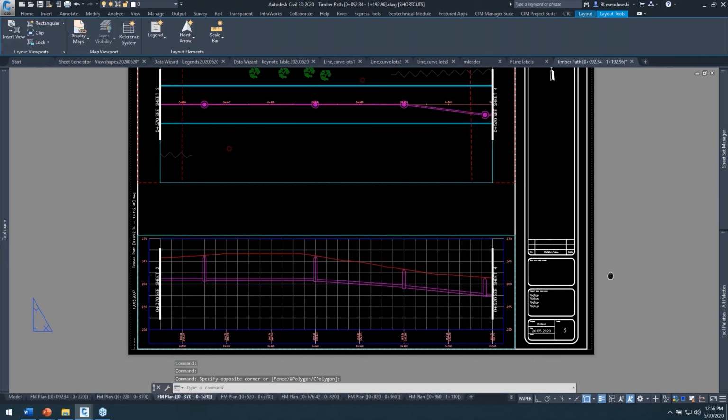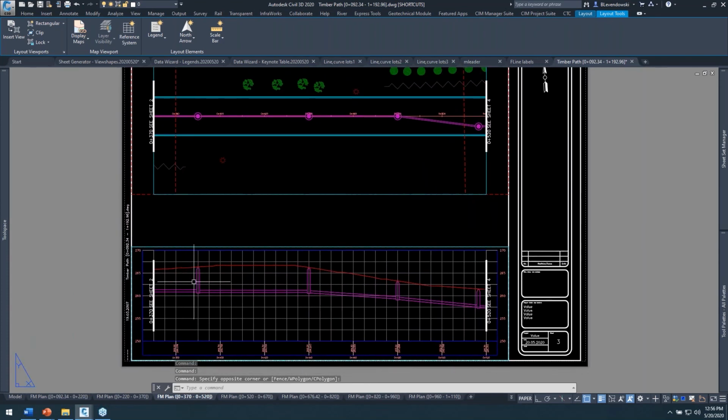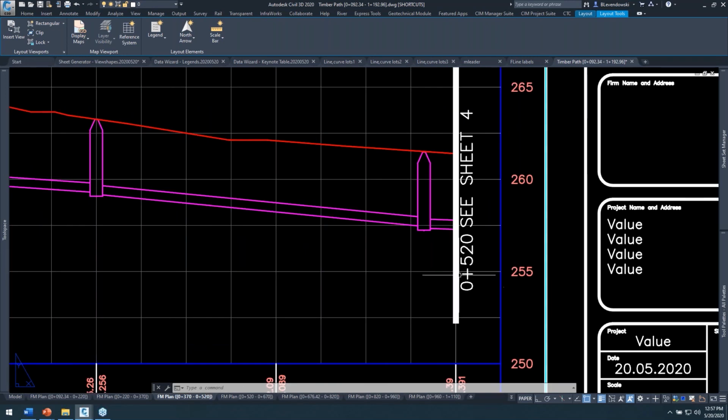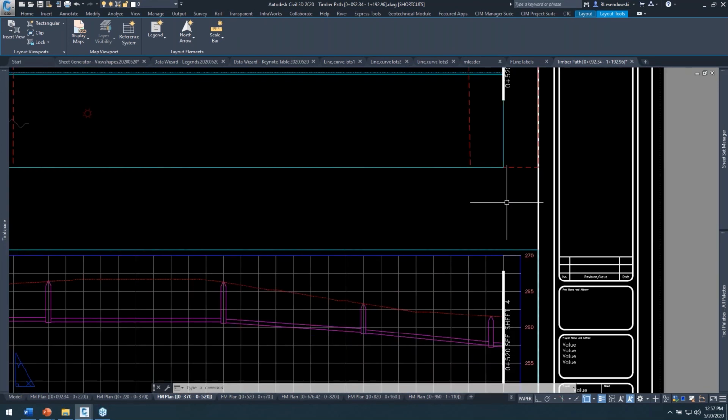And so there's my sheet. Okay, now where these land, it's all up to you. You get to control it based on those print blocks. A number of the other things here, we said we did profile match line blocks. We can even do masking in that buffer area. So notice that I want to show some grid beyond this, but I don't want to see objects beyond that. All that is handled in the tool set.